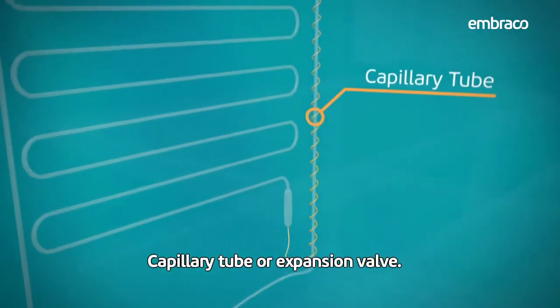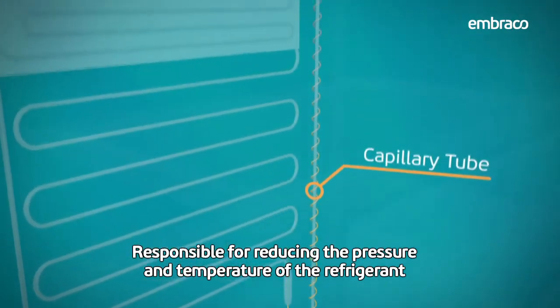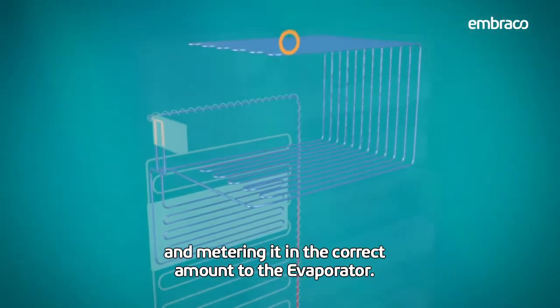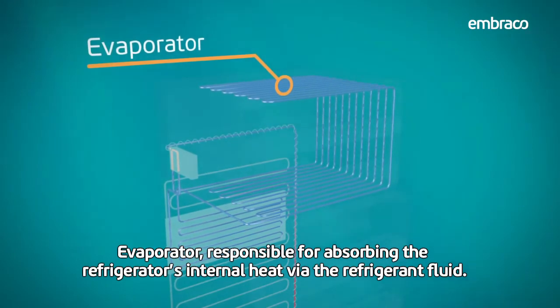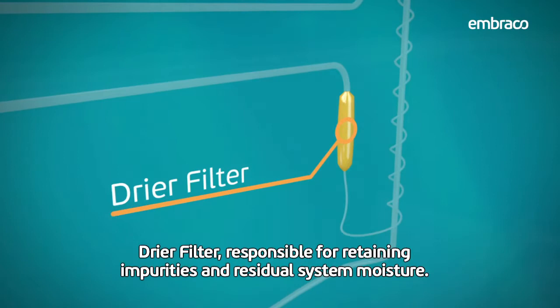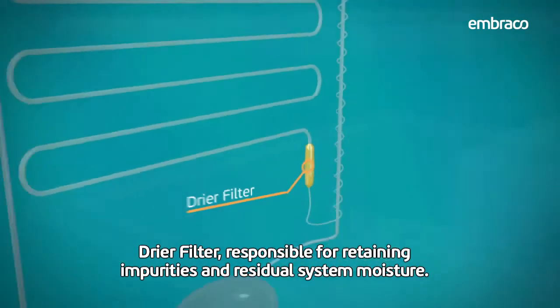Capillary tube or expansion valve, responsible for reducing the pressure and temperature of the refrigerant and metering it in the correct amount to the evaporator. Evaporator, responsible for absorbing the refrigerator's internal heat via the refrigerant fluid. Drier filter, responsible for retaining impurities and residual system moisture.